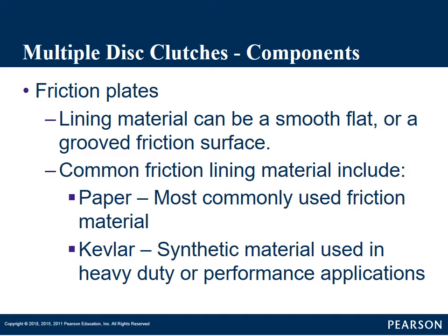You put it in gear, these clutch plates apply. That's the most common place you will find smooth clutch discs, fiber clutch discs. Not the only place, but the most common one. But if they have a grooved friction surface, that's usually used on clutch packs that get applied while the vehicle is moving.